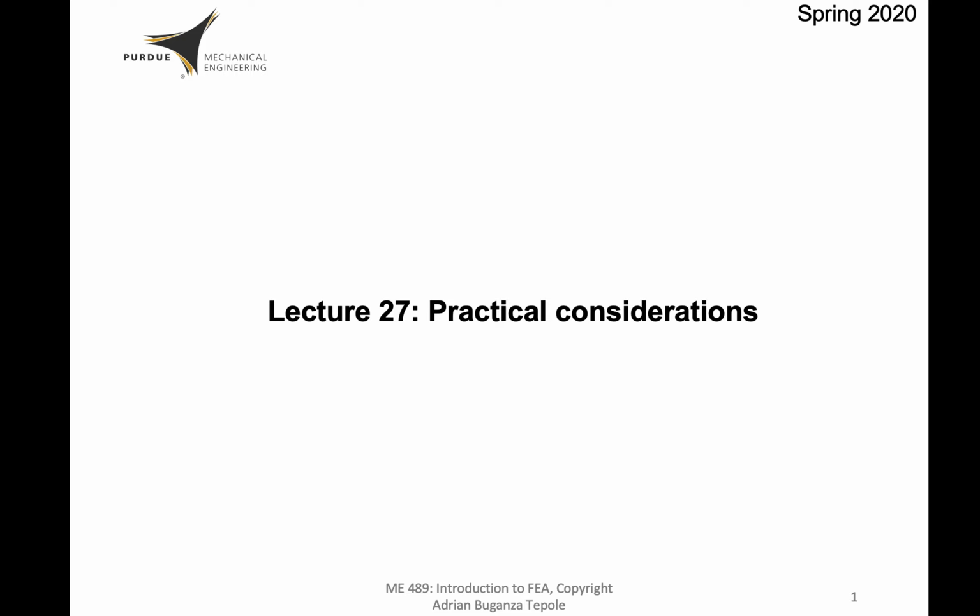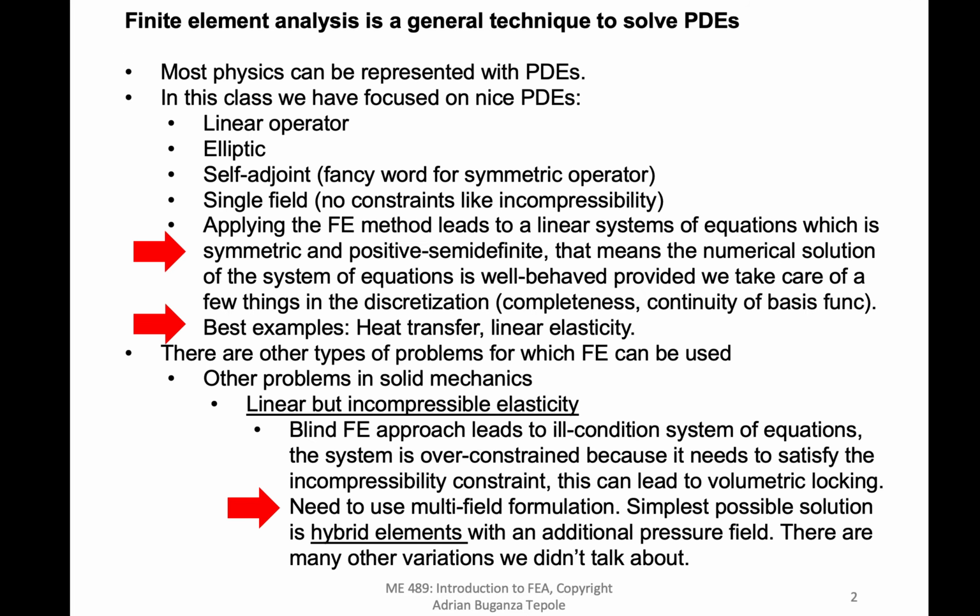And what I want to say, first of all, in this lecture is I want to talk about what other problems you can use the finite element method for that are beyond heat transfer and linear elasticity. As I said at the beginning of the class, most physics can be represented with PDEs. Usually you will get them in the strong form, so the classical form of the boundary value problem. And then the FE methodology allows you to turn it into the weak form in order to get the system of equations and solve it.